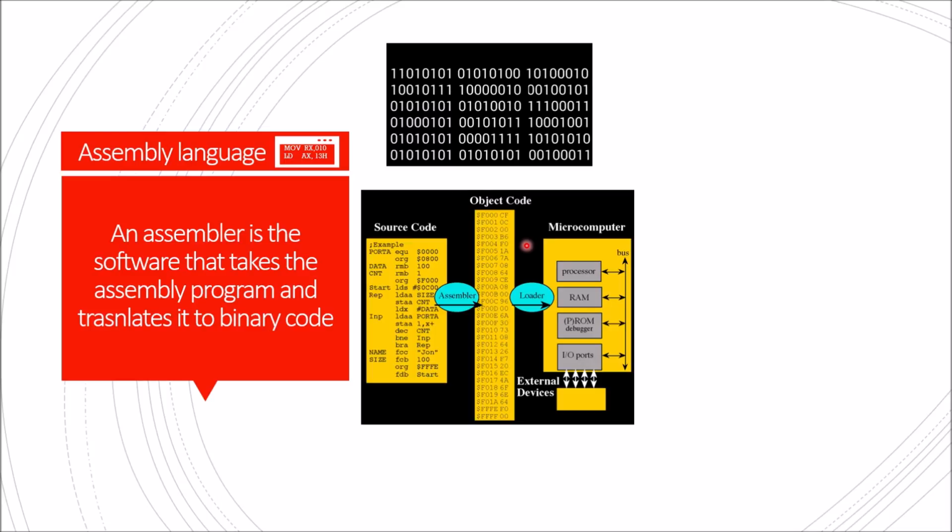So we have already reviewed, we used mnemonics, which are short text forms of these binary instructions. These are translated from the source code, that is the program, using those particular instructions in this language. It's translated by the assembler to binary code, which is also called object code, and will be loaded in a particular processor or computer by the loader.